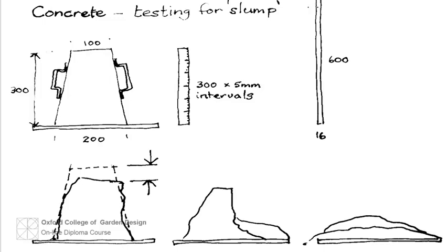Steel reinforcement comes as bars and welded steel mesh of various diameters and sizes. For example, A142 mesh is sometimes used to control cracking in concrete drives. Ferroconcrete is a mortar reinforced with a fine wire mesh. It is suitable for the construction of small garden free-form ponds up to 3 or 3.5 meters in length.